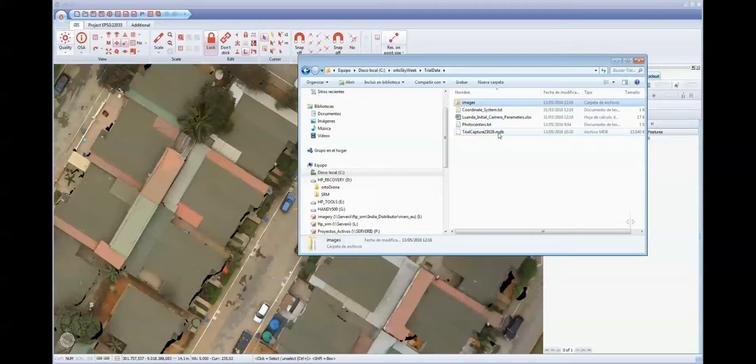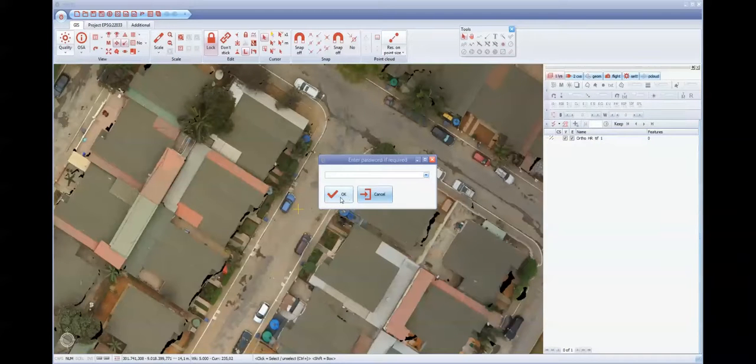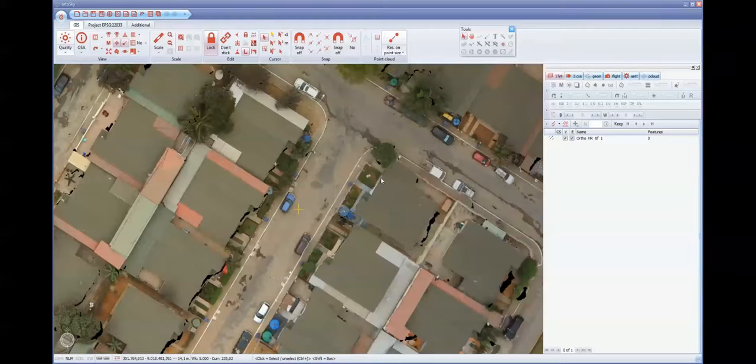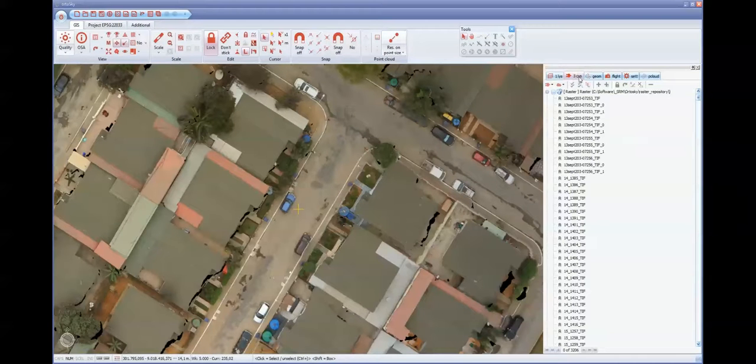Now we are going to load the MDB for capturing geometries. In this folder we have this MDB, trial data, with this number 23029, which is the coordinate system of this information. It is another coordinate system, but we can use it for the test of the system. Directly, we drag and drop. Press OK. If we have a password for the MDB, we have to introduce it. It's not the case here.